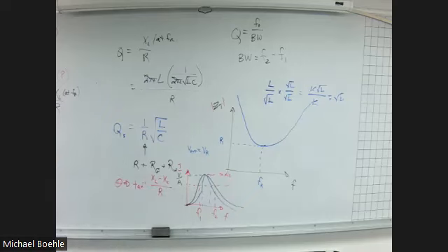The real part. So at low frequencies, capacitive reactance is larger, resulting in an impedance that is negative. That's a negative angle. And therefore, the current will lead. Talked about that earlier. Passive, active. Above resonance, the inductive reactance is bigger, and I end up with a positive angle for my impedance, and therefore a lagging current. Well, at resonance, because those two are equal, the inverse tangent of 0 divided by R, basically the inverse tangent of 0, is 0 degrees. You have no phase shift.